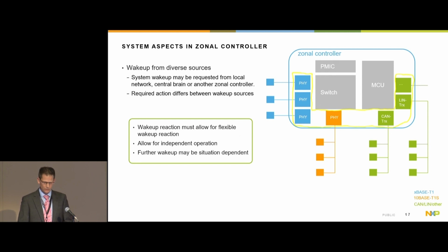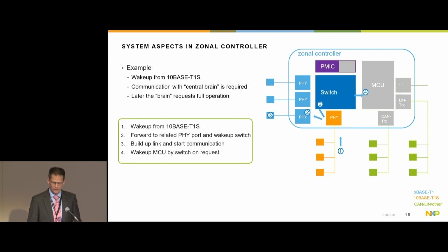And how this can look, I show on this slide, which is the last one. In principle, just as an example, you get a wake-up here from the PHY side. This one is waking up the switch and probably also starting the PMIC to make sure this side is supplied.